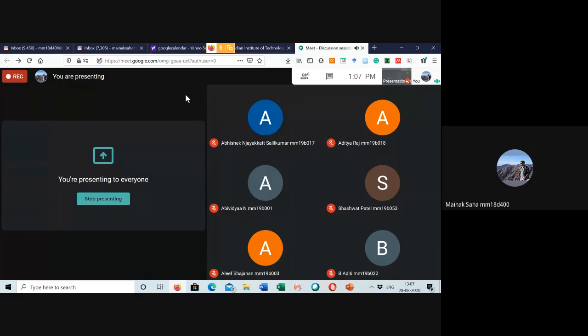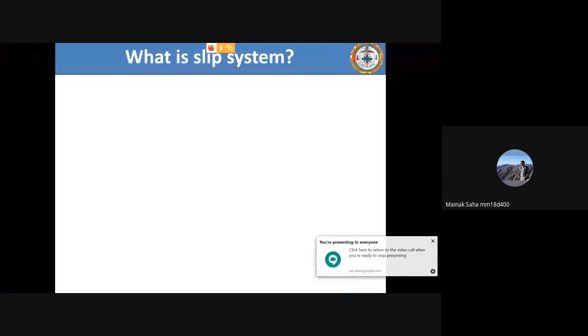So the Burgers vector is nothing but the minimum distance traveled by the atoms on the slip plane in the slip direction during plastic deformation. If plastic deformation occurs by slip, that is the Burgers vector. So if that is the case, the definition of slip plane stands very simple.